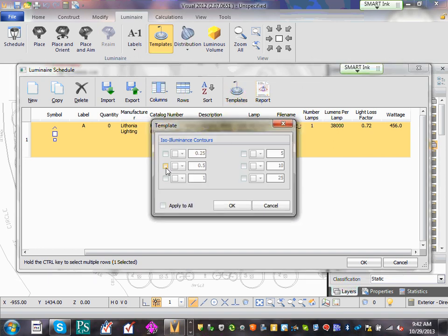This is gonna help you design your parking lot. Typically they give you all these values. These are all foot candle values. Usually a site is around 1, you want a minimum of 0.5 usually. 0.5, yeah, minimum. And we want 4:1 uniformity, which is actually pretty good for metal halide. So I'll use this 0.5